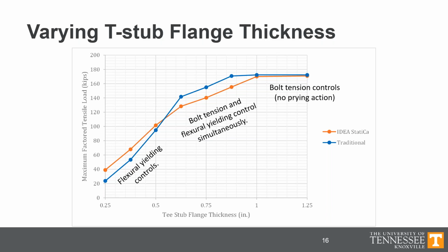For the thickest plates, where only tensile strength of the bolts controls, so in this region up here, there's no difference between IDEA StatiCa and the traditional calculations. This is expected because there's no prying action in this region, and IDEA StatiCa implements the AISC specification equations directly.